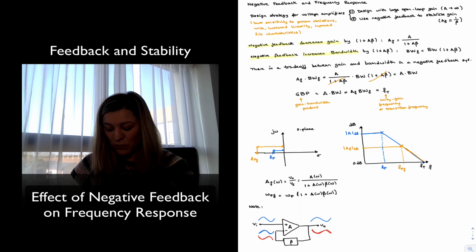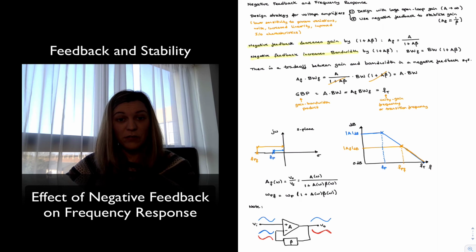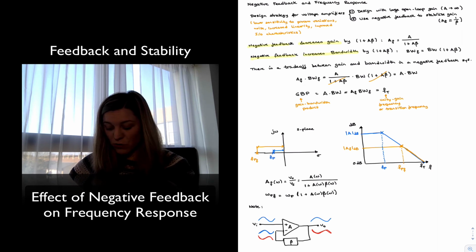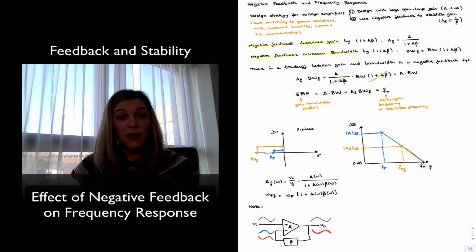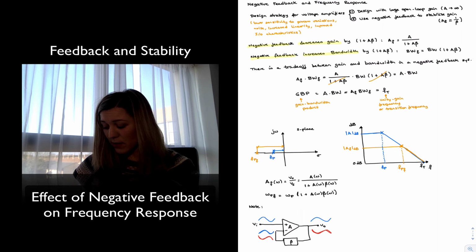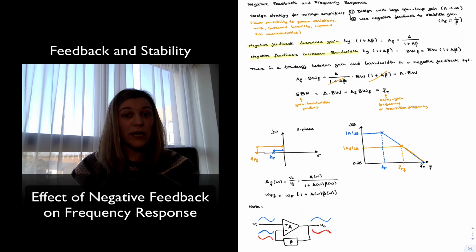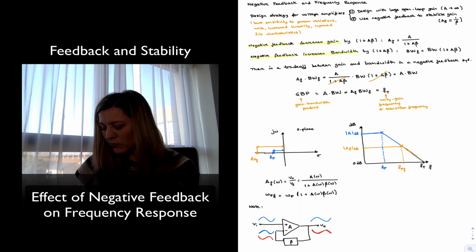Now when I subtract my positive signal minus this signal which is out of phase, so it's basically opposite, I'm going to get, minus minus is equivalent to adding the two signals together, or having twice my input signal. And so I can see that my signal, in going through the loop, sampling the output and coming back, my input signal has essentially doubled. And then it's going to run through the loop again, and if the same thing happens, it's going to keep increasing. And the idea is that I'm going to have an ever-increasing oscillation in my signal.